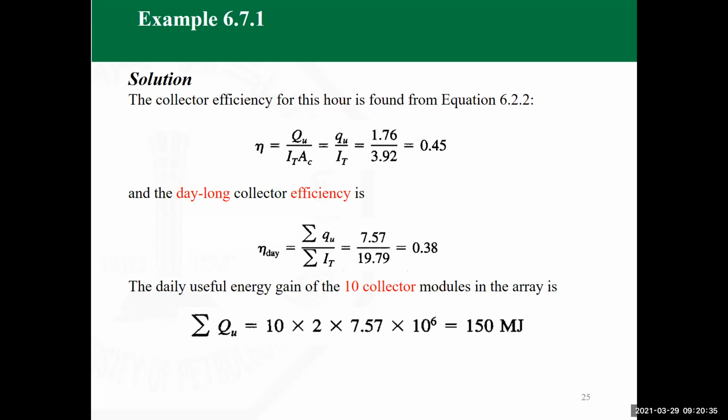What we need to do is to study the possibility of replacing this system by solar collectors. So I will be providing you with the number of rooms and the expected number of occupants, and from all of this, what you need is basically how much water needs to be heated every day. You are going to calculate how much energy will be needed for heating the water. And then the question would be, what percentage of this energy do you need to provide by solar energy? This is what we refer to as the solar fraction.